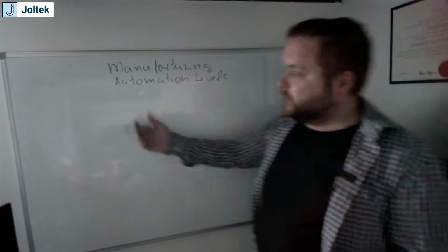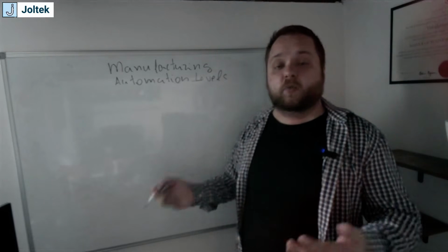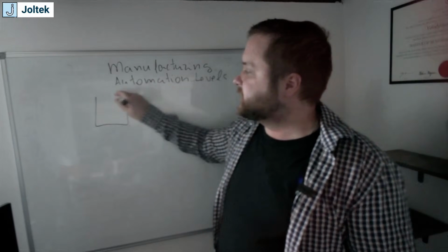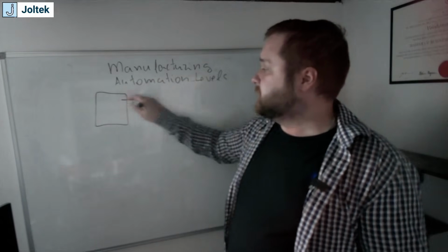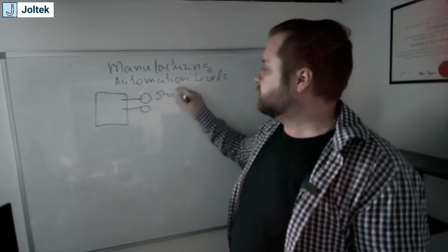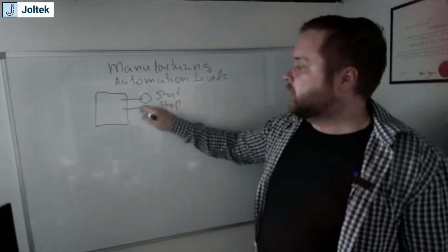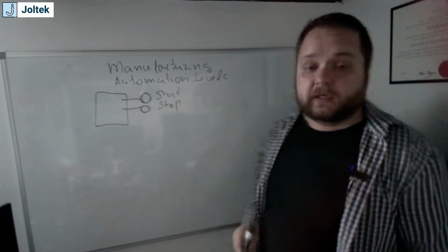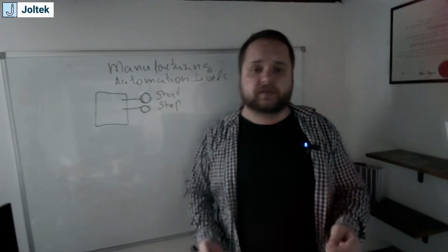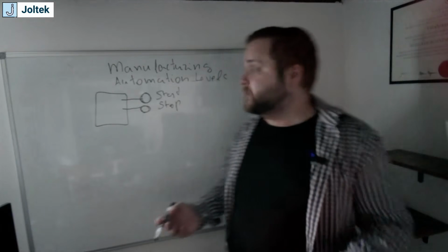But ultimately, I want to take a step back and talk a little bit as to why we're going the way the networks are. So in the past, when you had a VFD, we've discussed this a little bit, a VFD can be started by a start button and a stop push button. So start and stop. And so in this case, as I've mentioned a little bit earlier as well, you get very little diagnostics from your device, right? And the same goes for your sensors, the same goes for your load cells, the same goes for your HMIs and PLC, to be honest with you.